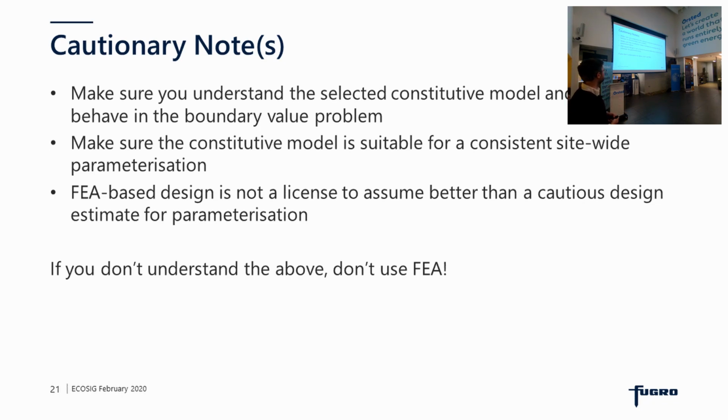And that leads me on to my final cautionary note: the use of FEA-based design, although we know, and it's been well publicised, it can give us gains in terms of reduced foundation sizing, is not or should not be a licence to assume better than cautious design parameters. Just because you're using a model which gives a better representation of the physics of the foundation problem, it doesn't mean that you have to throw all caution or conservatism out of the design process. In fact, arguably, it's even more important to understand the level of conservatism in your constitutive model parameterization, because that can be quite a complex thing to try and unpick to define a factor of safety on a foundation.